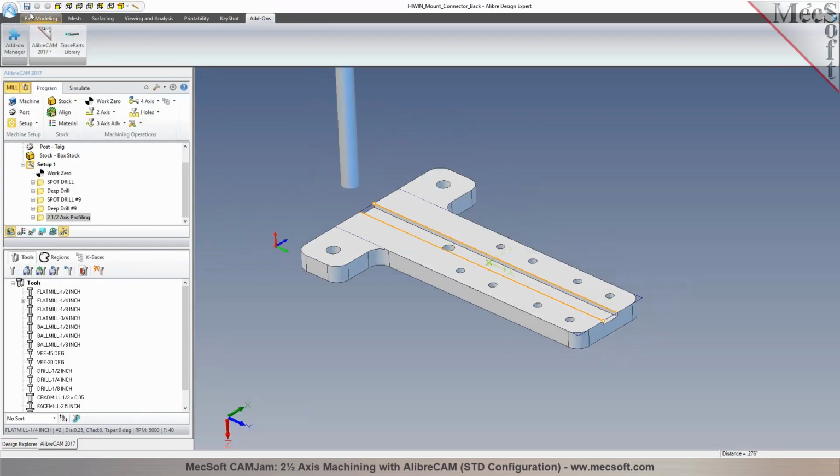So now we got through the profile. The final thing you want to do is cut the profile around the periphery of the part, and you can choose what cutter you want to use. So you want to see what's the smallest radius on the part. This is 197, so a 1/4 inch tool or even a 3/8 inch cutter might work well.